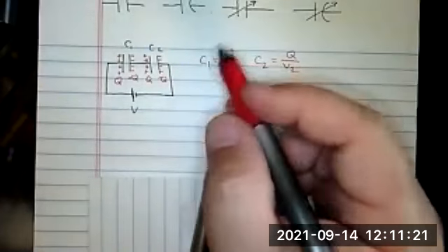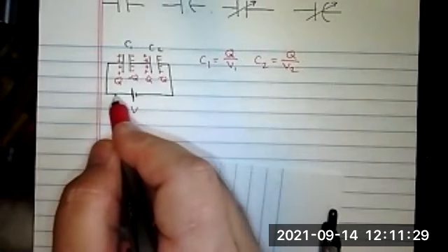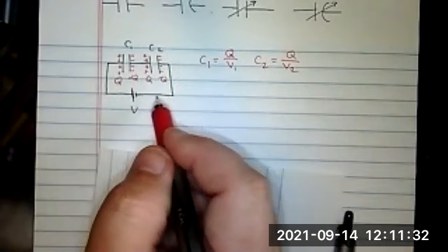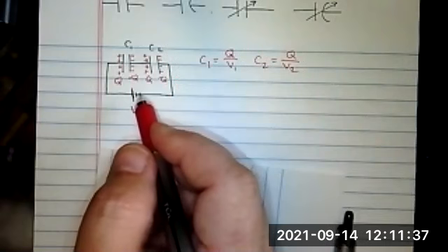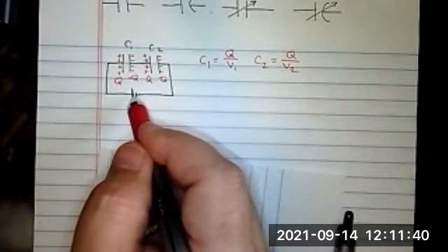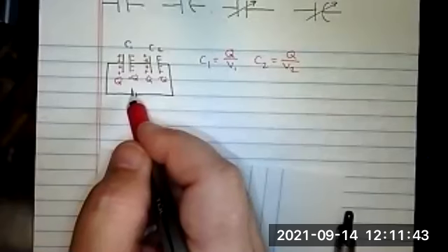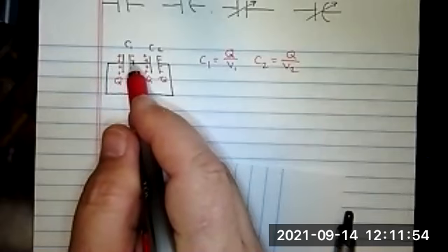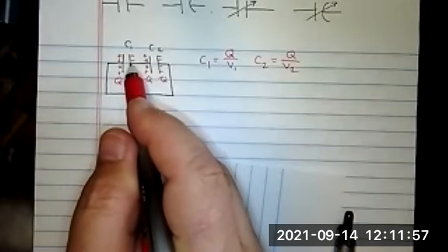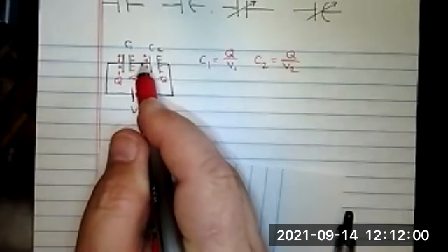And since Kirchhoff's loop rule, which we'll learn later, basically conservation of energy, suggests that if you go up in energy and then go down and up and down, if you ever end up back at the same place, the total energy difference must be zero. So I went from here to here and jumped up in energy per unit charge. Remember, joules per coulomb is what the volt is, to positive V joules per coulomb. And then I went down V1 because I went from positive to a negative. And now I was down V minus V1.